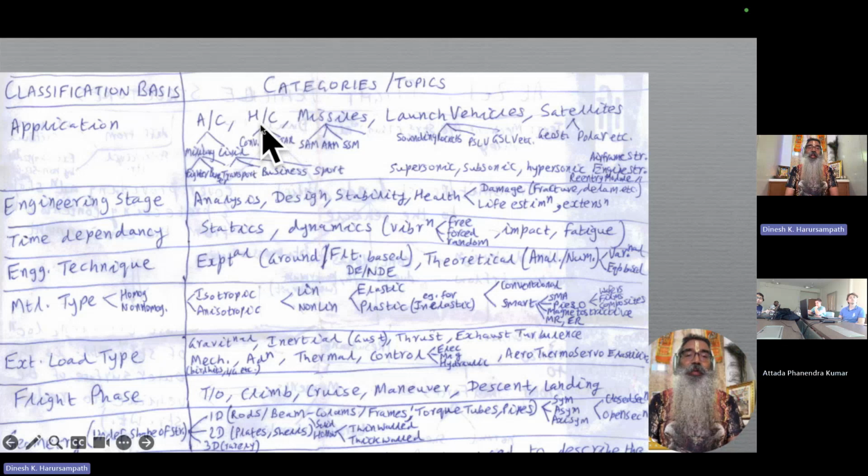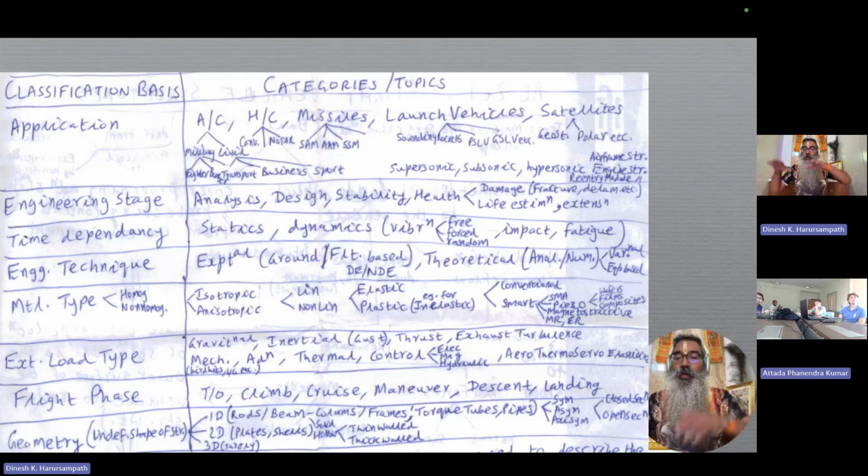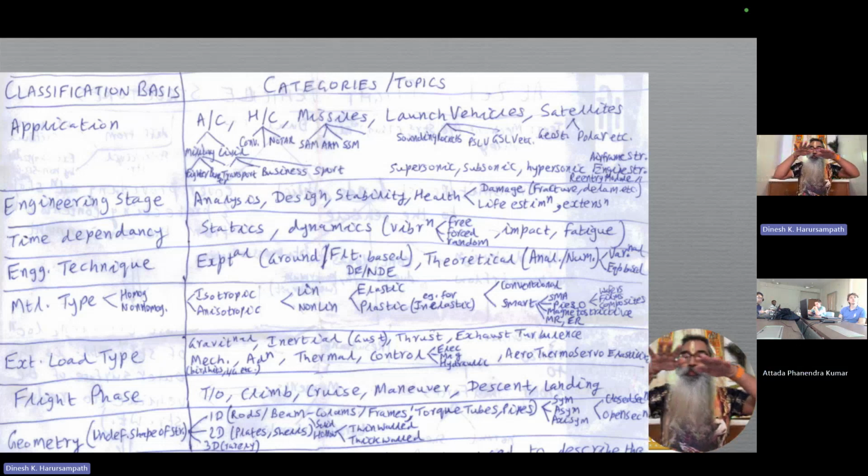Again, that's just the main rotor, but the main rotor is not all that the helicopter is. Apart from the fuselage, it also has another complication: because it's a rotating lifting surface, we need to balance the torque. Otherwise, the rotor will be rotating in one direction, and the helicopter will start rotating in the other direction, which will be absolutely inconvenient for the pilots and, of course, the passengers. So you need to balance that torque, for which you have anti-torque systems, conventionally the tail rotor, but you can also have two rotors, either side by side or front and back, just like doubles on a cycle, called a tandem configuration, and they will be rotating in opposite directions, creating opposite torques, so that they get balanced overall as far as the helicopter itself is concerned, right?